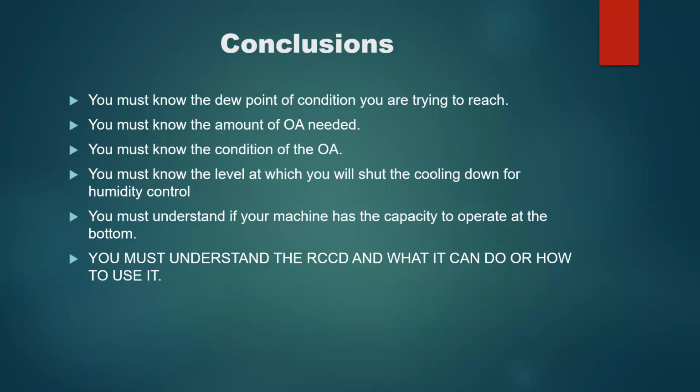Then if a little bit comes in the building, you've got enough heat in the building to make up for it. Or in the case of a restaurant that had an issue with both moisture dripping off the grills and all kinds of stuff, they didn't have any makeup air. So anytime you pull it into a negative pressure, all that air, moisture, is going to come in through areas where you don't want it to come in. By putting in a positive pressure, you're pressurizing it with conditioned air, and now you're going to mitigate it.